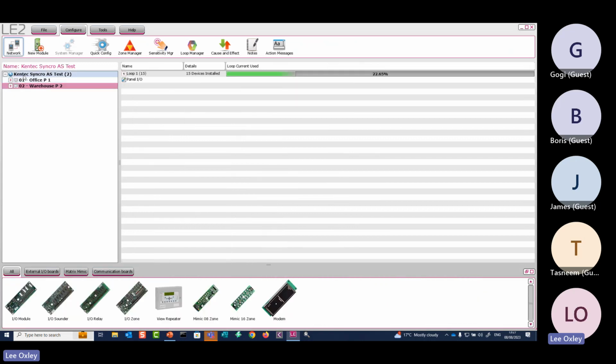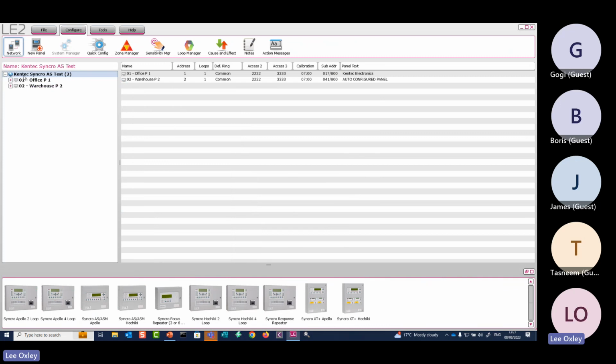So you're going to go to site. They've built another building called dispatch, for example. So you need to add another panel, panel 3 let's say, because I've got panels 1 and 2. You get your panel out of the box and put it on the wall. You've got your network card, and you've addressed it as address 3 with the binary DIL switches. That's fine. You've powered the panel up, you've got the batteries in, and the panel's now powered up as address 3. It's going to show unexpected network card, so you're going to open the write enable switch, go to level 3, and then learn the panel.